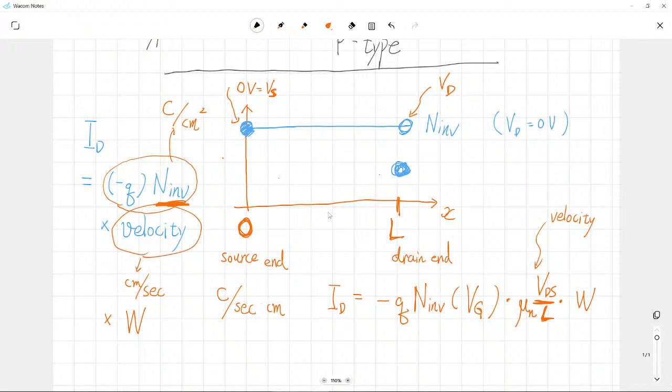When we have this negative sign, the assumed direction of our current is just the positive x direction. However, please think about our convention. What was the convention for terminal current? Terminal current always should be in the incoming direction. So from the viewpoint of our source, this is the positive direction.